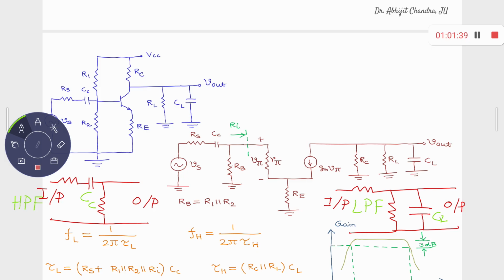So once again, sometimes in your circuit you have to use some load capacitor, and accordingly you need to find out the value of the load capacitor. What should be the effective value? Because you have to ensure that it should not interfere with the higher cutoff frequency you already have, some 20 megahertz, some value. So accordingly, here what I find, this higher cutoff frequency is given by 1 by 2 pi tau h. But what is that tau h?